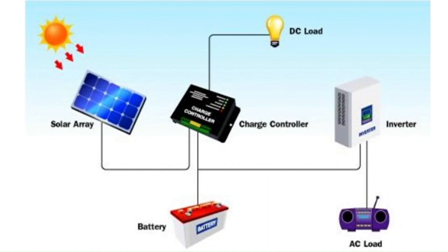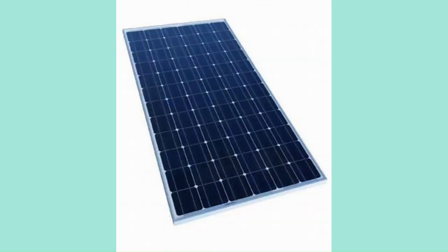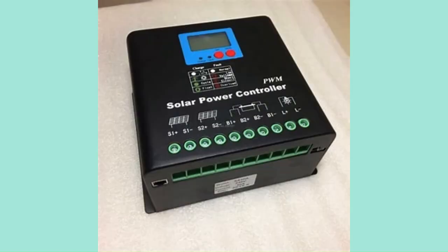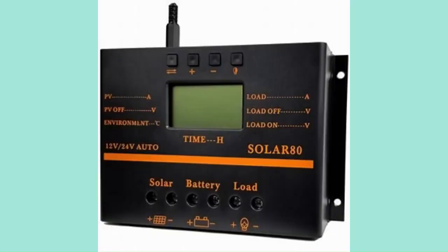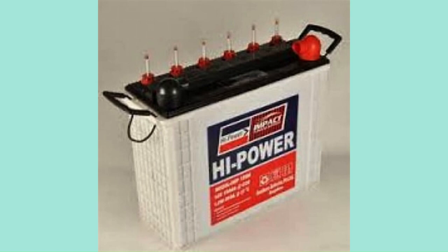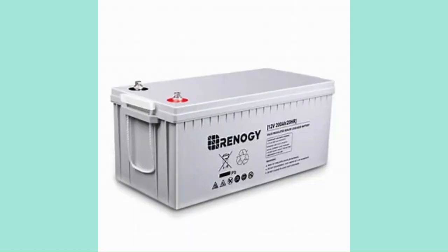The components of the solar photovoltaic system are as follows. The solar module, which transforms sunlight directly into DC electricity, is a crucial part of any solar PV system. The solar charge controller regulates voltage and current from solar arrays, charges the battery, prevents the battery from overcharging, and also performs control over discharges. The battery stores electricity produced from solar arrays for use when sunlight is not available, at nighttime, or for other purposes.